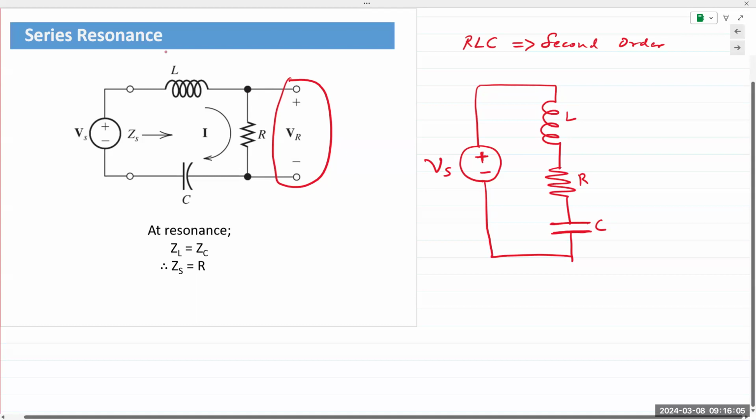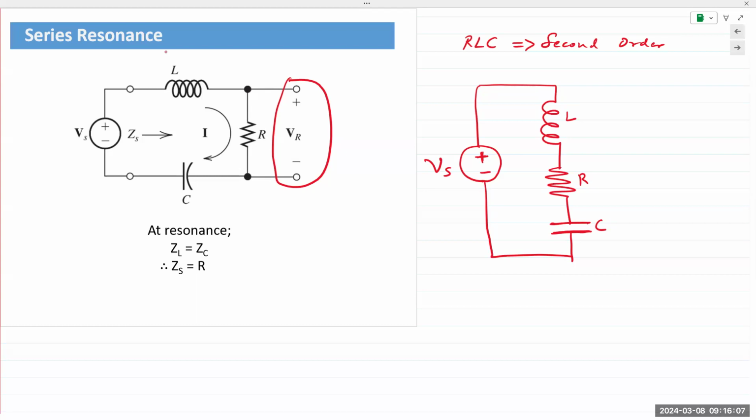Okay. And that is one of the reasons why you can see a voltage or current that is larger than the source could appear in the circuit, right? If you have energy that is stored inside the inductor and capacitor, depending on the circuit configuration, that stored energy summed up along with the source would contribute to a larger voltage or current. Does that make sense?